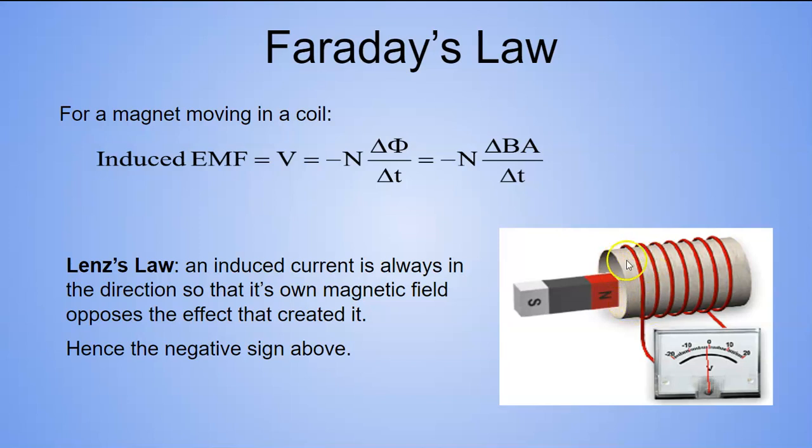So right here, that coil has a certain area. If we somehow were to make that bigger or smaller, that would change the area, and that change in area over time would induce a voltage. Maybe I'm rotating the coil, and that's presenting a different face to the magnetic field. Maybe I'm rotating the magnet, and so magnetic field lines are sweeping. That would change my B instead of my A. But anytime I change any of those factors, I'm going to get a voltage induced here, and that would make a current flow, makes electricity like we did.